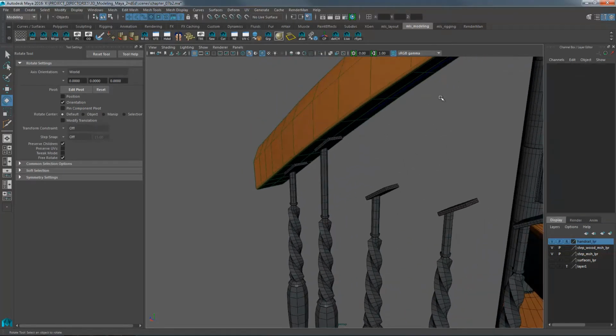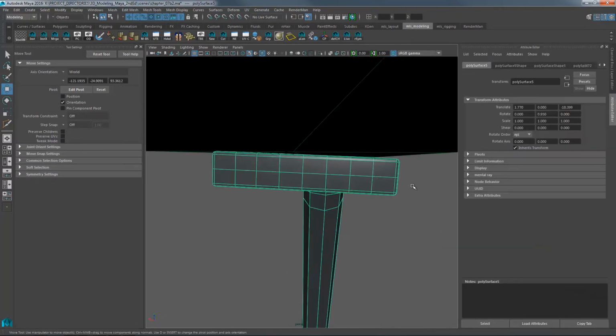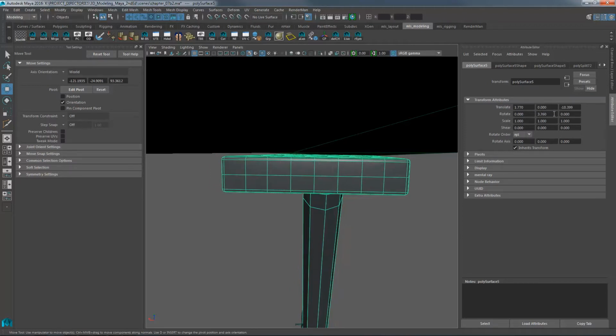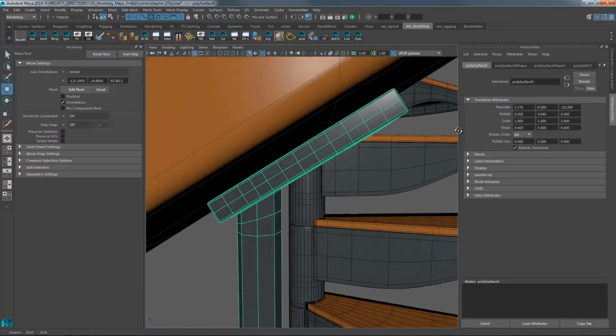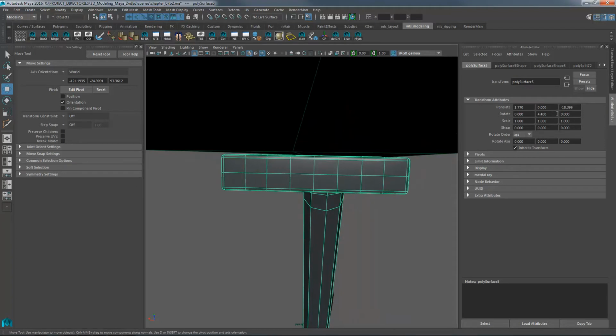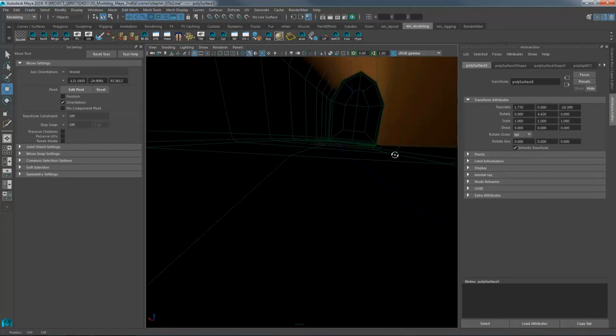Take some time and move those all up there and see how they hit the handrail. Yeah, so here I've moved the third one up, and you can see that it's at a slight angle. It's not touching on one end. So here I've got the attribute editor open, and here it is at 0 degrees rotation. So if I rotate this just by control clicking and dragging, nice small changes. You see how it kind of evens it out. So there's an even space. So just a small amount of turning on the y-axis.